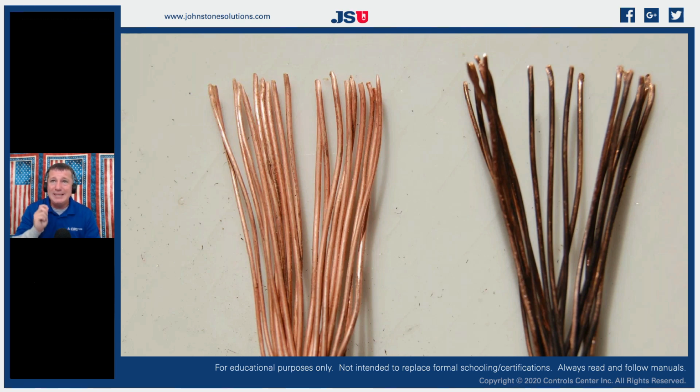So it brings in a new layer of understanding of wires and how we communicate through those wires. Because if I have a single solid conductor and I have oxidation on the outside of it and it works fine for legacy wiring, pushing current through it, and then I use that same solid wire for communication on my new outdoor unit and indoor unit that I just installed, I won't be able to talk along that solid surface as well because of my additional patina and corrosion.